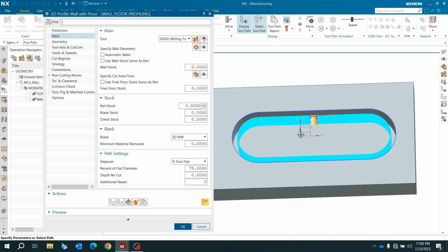Why am I suggesting this? Because if you go directly for more material, the load on the cutter or the spindle is more. You may observe it on the machine. At that moment you have to safeguard your cutter. If you want to increase your tool life, then you have to give multiple passes.